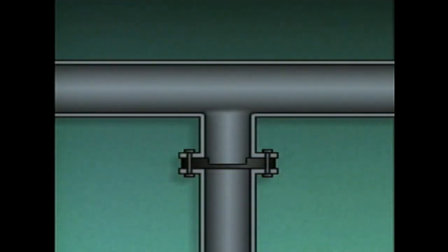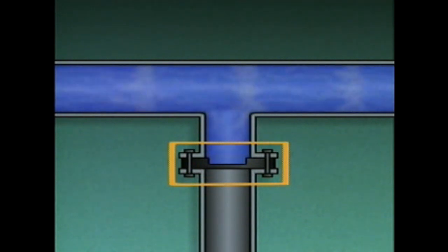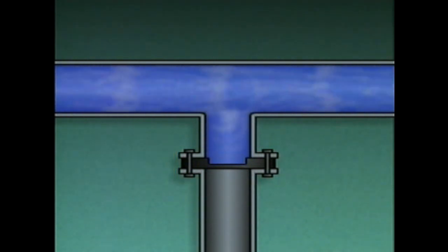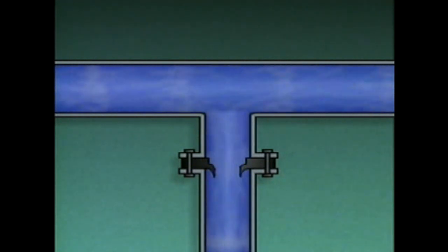Under normal operating conditions, fluid flows through the pipe, and the rupture disc blocks the flow through this relief line. If the pressure in the pipe exceeds a certain value, the rupture disc breaks. This allows some of the fluid to flow through the relief line, which relieves system pressure.